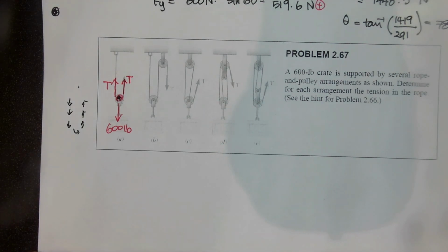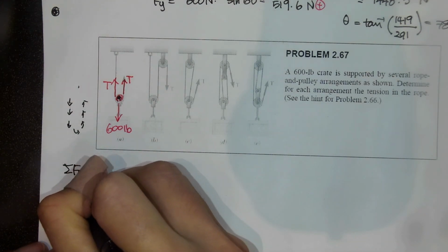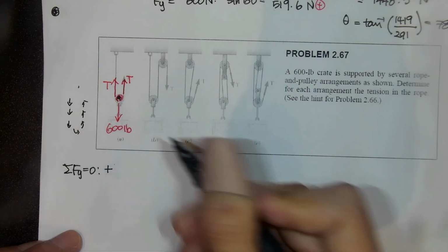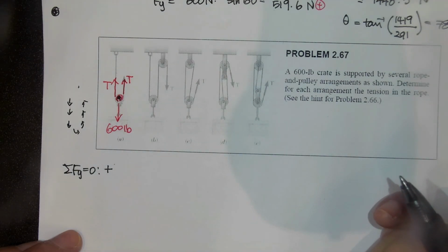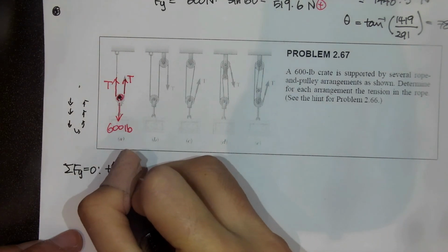Okay, then we have the complete free body diagram, and there is no x component, so we can set up Fy equilibrium equations, y direction only, right? Then we assume a positive direction, either upward or downward, it's your choice. I choose upward.